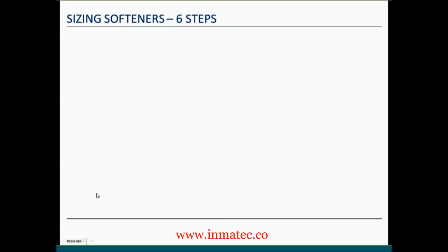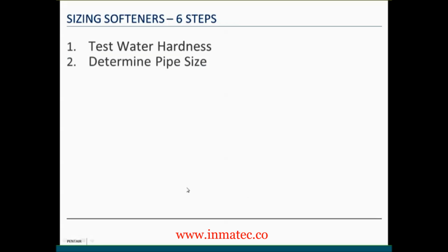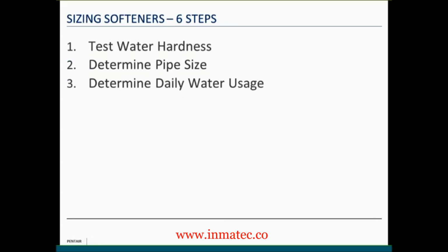Sizing water softeners. There's 6 steps to this process. A, we need to test the water hardness. We need to know how much hardness we have to remove.